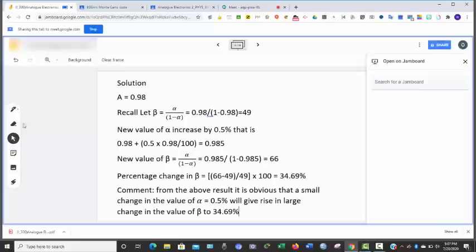Normally what we have for HFE is something like this. We have it like this: HFE is equal to IC over IB. So for some of the digital multimeters that we have, you can measure your HFE. Once you are able to identify your collector and your base, take the collector, put it in the hole for collector, take the base, put it in the hole for base. If you do that, you get your HFE.